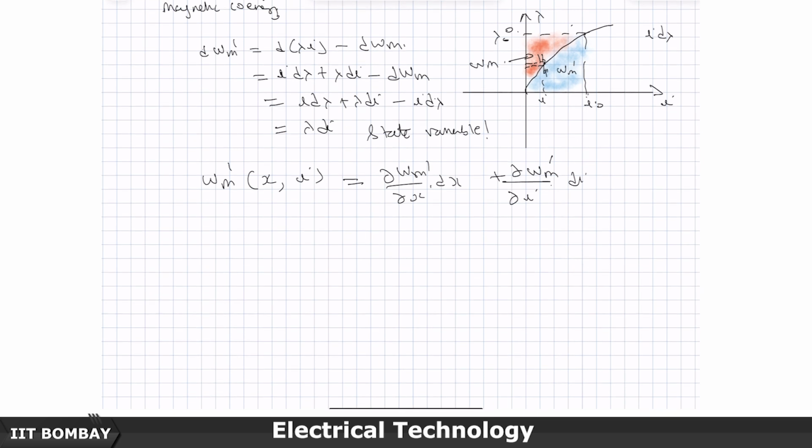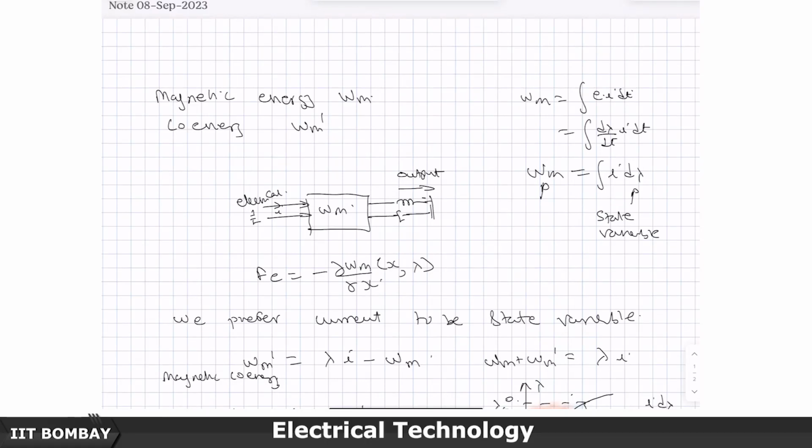And when you are talking of a machine, my discussion that power input directly goes as magnetic field energy holds only so long as there is no mechanical work being done. If mechanical work is being done, then whatever incremental electrical power you push into the system, part of it will be stored as magnetic field energy.